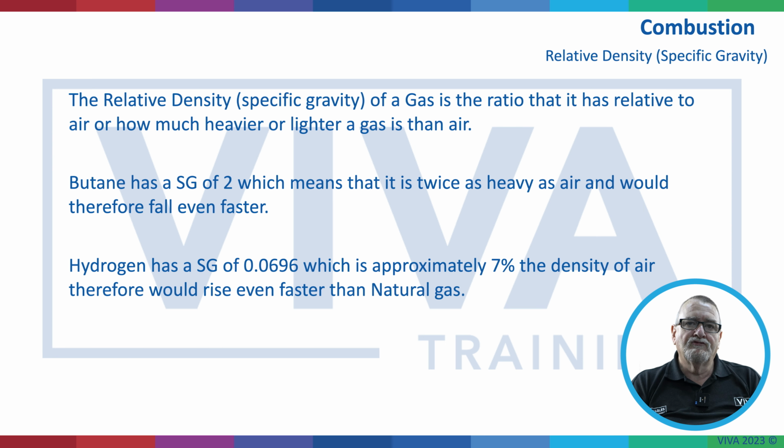And then going into the future, there's a lot of talk at the moment about renewable technologies and where gas lies. Well, as it is, we're using hydrogen. At the moment, we're blending it with natural gas. We've got an 80% to 20%, so 80% natural gas, 20% hydrogen. The future is talking about going full-blown hydrogen. In fact, there are some properties up in the northeast which are running on full-blown hydrogen. Well, hydrogen is 0.0696, so it's about 7% the density of air, so it's really, really light. That's why it floats up.